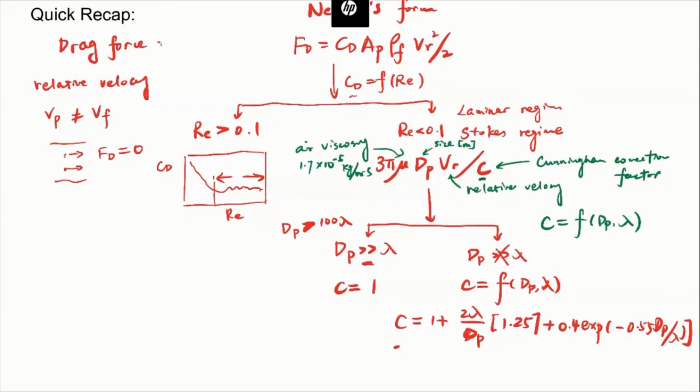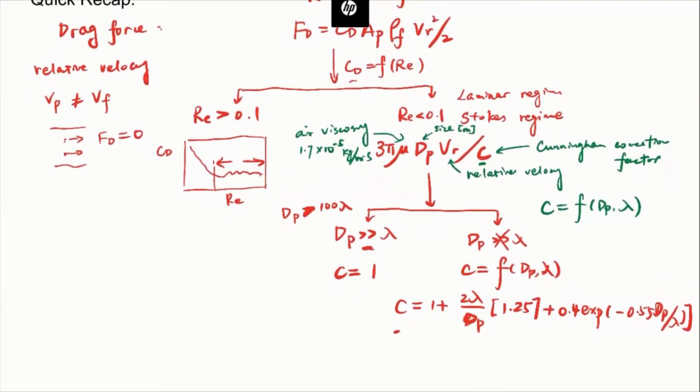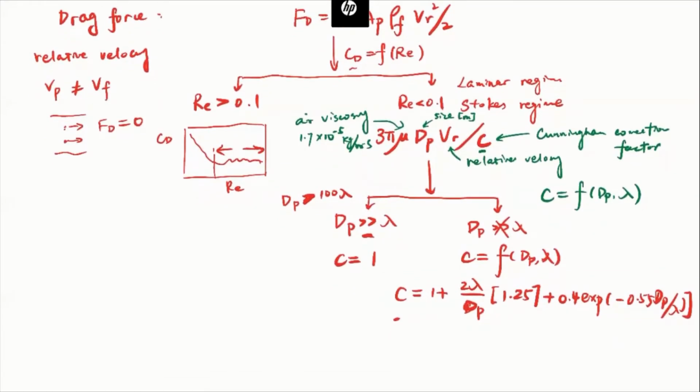So this is what we have gone through from our previous classes. With the drag force, we introduced an idea about the free settling of a particle. Whenever we talk about particle settling, we have force analysis. There's going to be gravity making the particle settle down, and the drag force to balance it. So we introduced an idea called the terminal velocity, or the terminal settling velocity.